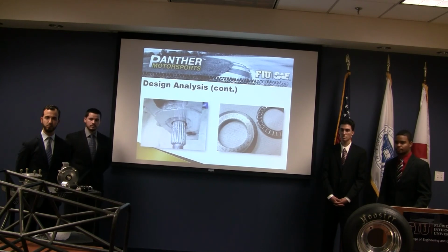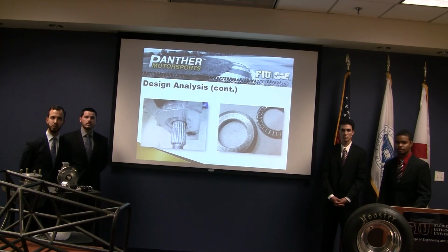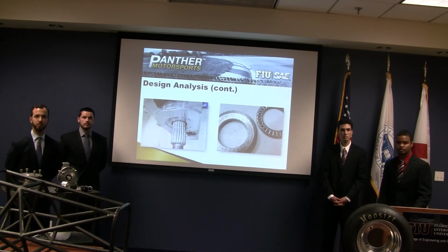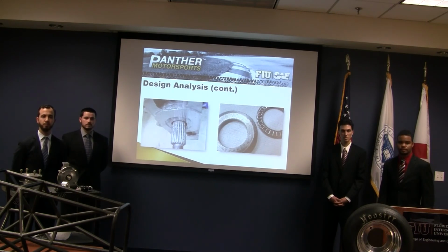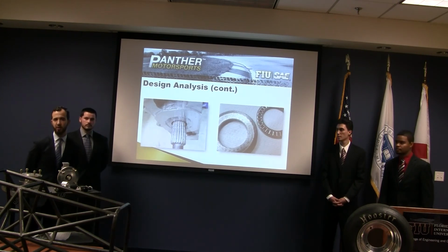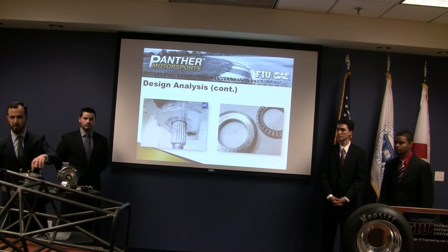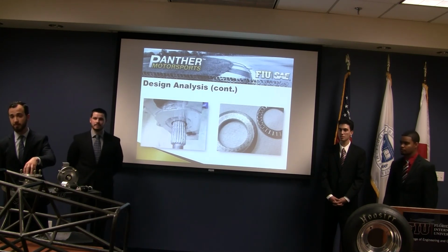But have you done any experimental testing on your new design to confirm? Not yet. Just a quick suggestion, you have the old one, right? You're not going to use that one anymore? Do some testing on that one, throw a whole bunch of weight on it and compare your simulations, and then you feel more confident with this one, right? So I mean, I didn't want to call experimental testing bolting it on and spinning it at the shop. Yeah, I understand. But the old ones were so bad you couldn't do that.